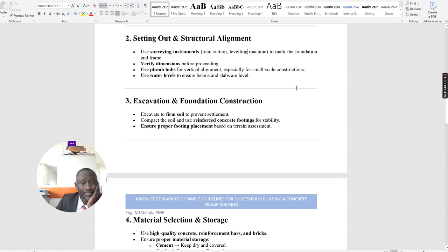It is very important that your foremen and those doing carpentry work get this right, because these columns are put in place before concrete works. They are aligned and molded by carpenters. The molds are put up by the carpenters, so they should do very good alignment, especially in the vertical direction. Then horizontally, the levels, that one also is okay. You can use a water level.